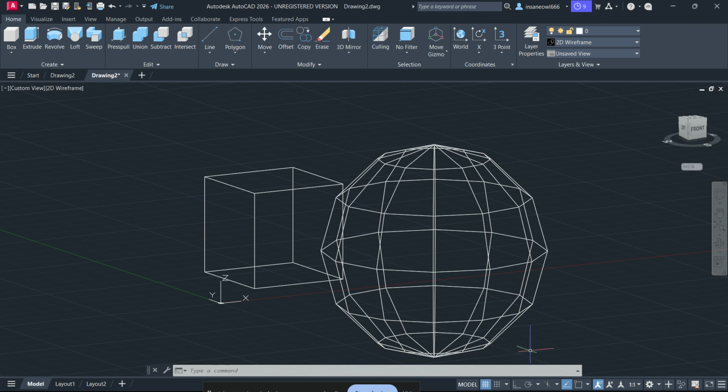If you are working with imported geometry, the issue may be even more common because imported solids can contain hidden flaws, surface inconsistencies, or bad topology. In that case, cleaning the body, checking validity, and simplifying the shape become even more important. Sometimes, the imported object looks fine visually, but still contains internal geometry problems that only show up when you try to combine solids.